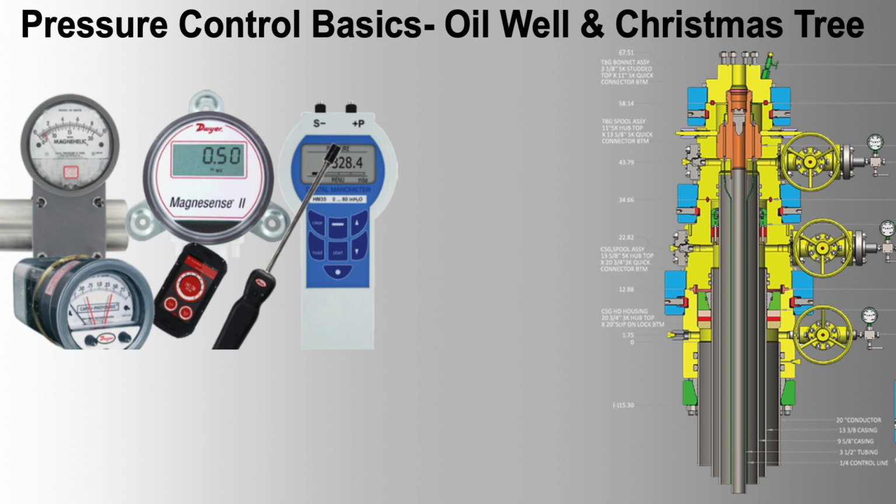Detailed explanation for each example. Example 1, wellhead pressure transmitter for sour service. Design. A differential pressure transmitter is ideal for measuring pressure differences across wellhead equipment. The use of Inconel 625 ensures the transmitter withstands the corrosive nature of sour gas. Selection. The transmitter's accuracy of ±0.1% ensures precise monitoring of wellhead pressure, crucial for safe and efficient well operations. Direct mounting with a remote seal protects the sensor from high temperatures and harsh conditions.